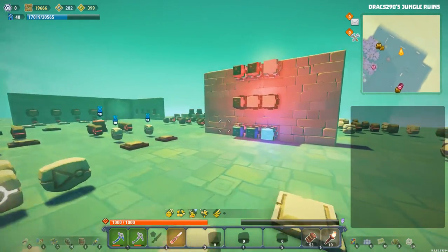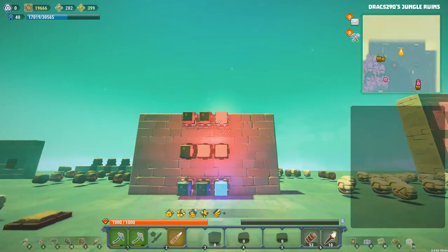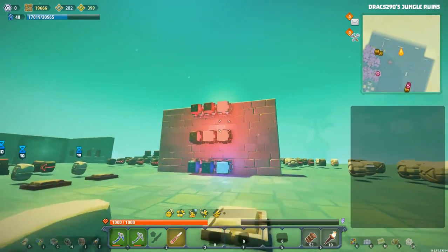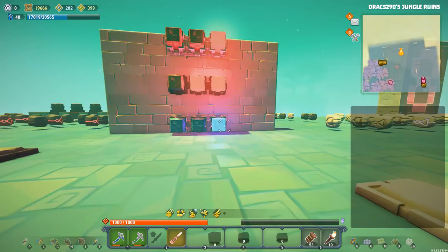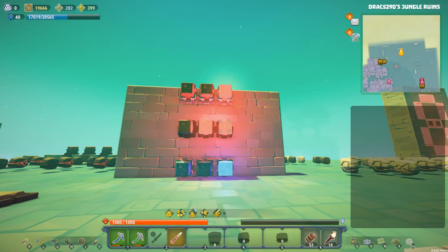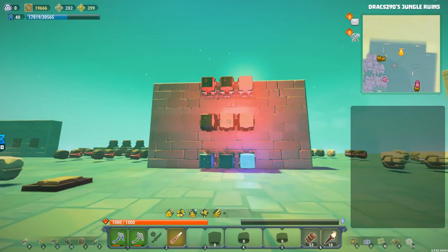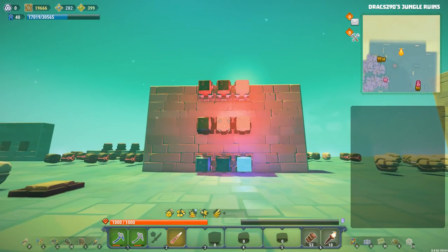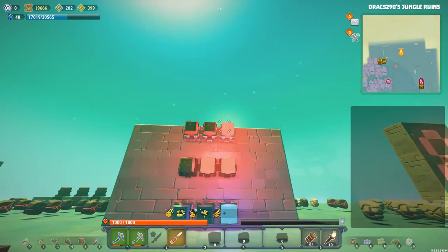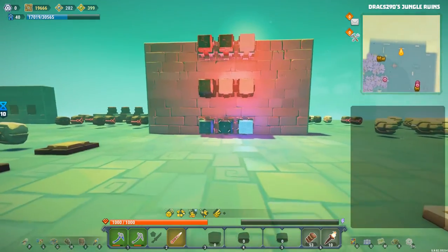So basically how this thing all works is we have a 3-bit counter here. So we've done counters before, and then at the top we've got a 3-bit sequencer, and once again we've done sequences before, and then we XOR these together to get the total output. So basically the way this works is that this light here in the counter, the first light in the counter, gets copied down to the first light in the output line, and then this output here is an exclusive OR of this, the second dot in the counter and the first dot in the sequencer. So if these two things are the same, this is off, and if they're different, then this is on.